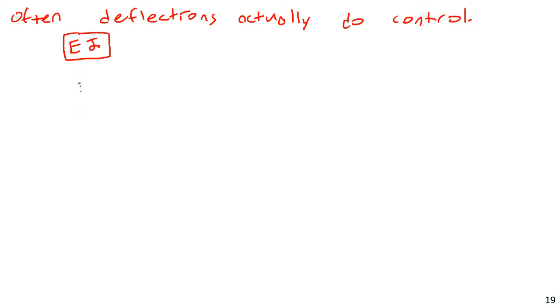That's going to be your 29,000 ksi modulus of elasticity. And I is your moment of inertia. This is your geometry, the property of the shape that's going to determine your deflection capability.